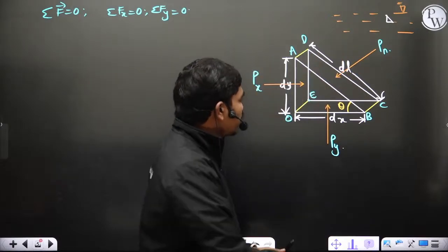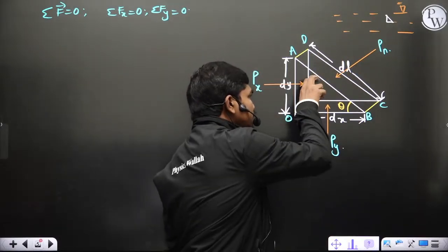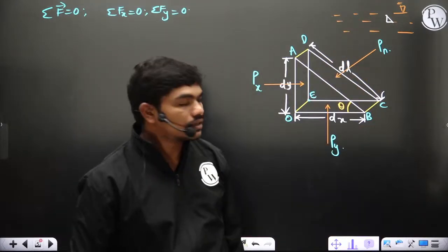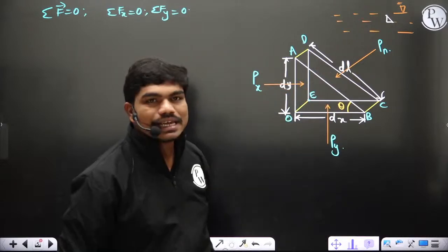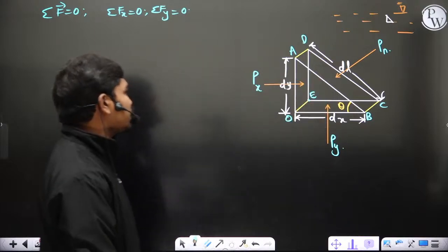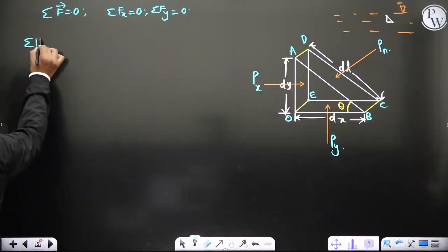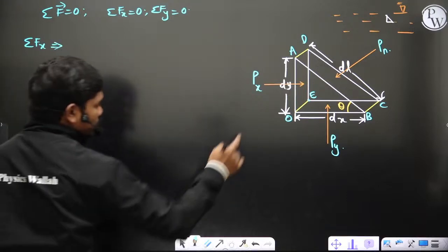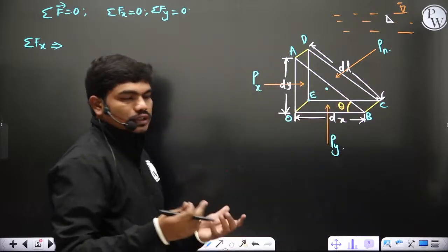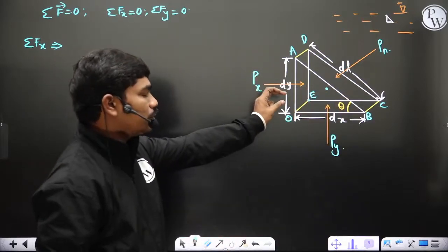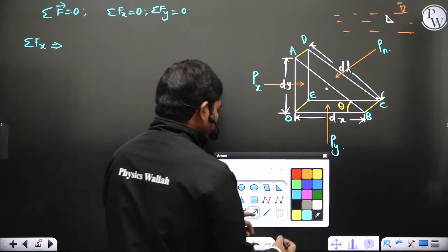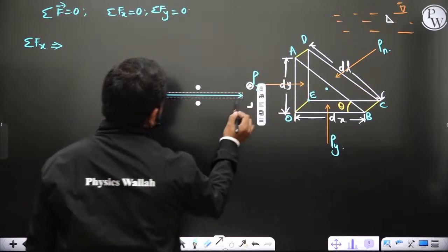Okay, so if that's delta, and you take this block size to be very small, for example, because we are just picking some small element from that, so this is dx, dy and this is dl. Obviously by Pythagoras theorem you can calculate dl is equal to root of dx square plus dy square. Okay, now if you add sigma Fx, generally assume that all three forces are meeting at the centroid, because it's a concurrent force system, for a small size of the block, obviously these three will actually pass through one particular point. Okay, so therefore if you do this analysis, for example,